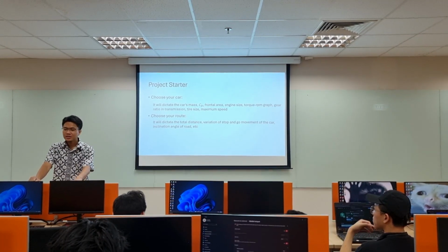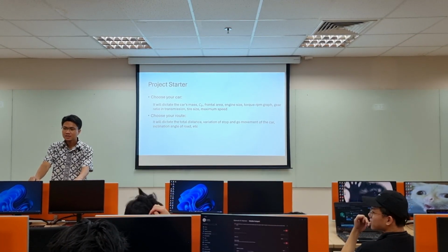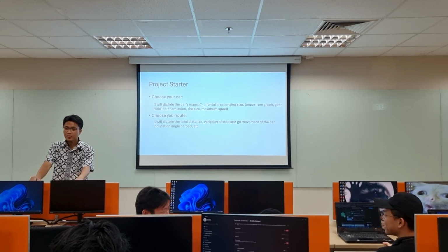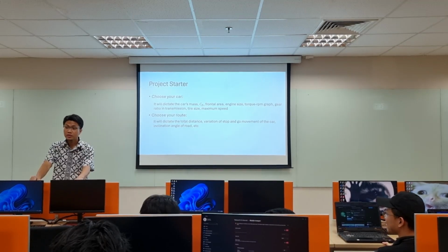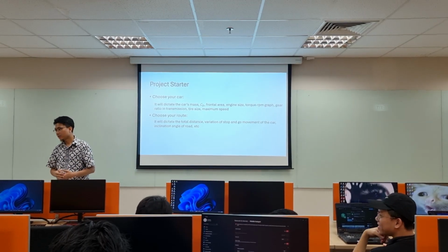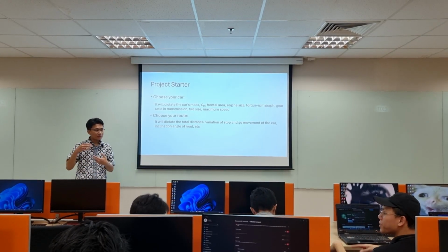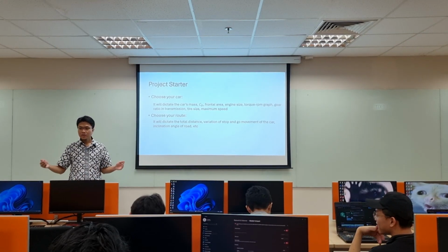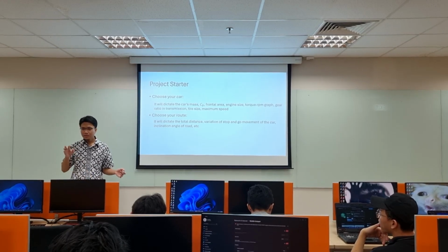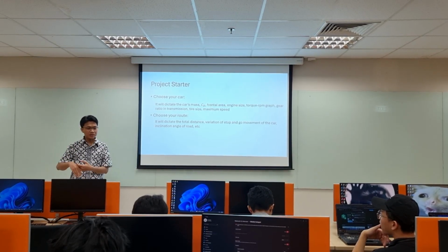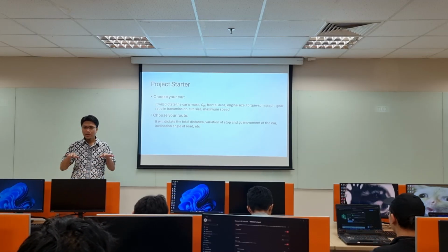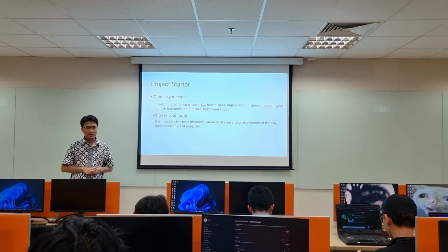So do you know what's the fuel consumption of that car? 115. Okay, so 115, he said. I think that's a reasonable value. So after you simulate it, you have to get roughly around that number. If your number is too much bigger or too much lower than that, something is not right with your simulation. So we have a guessing value in that case.